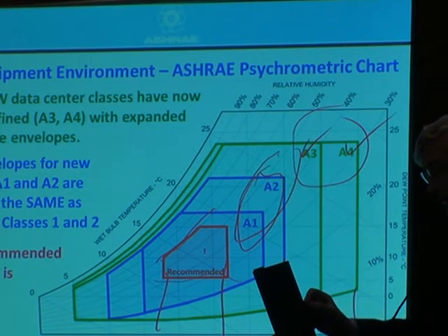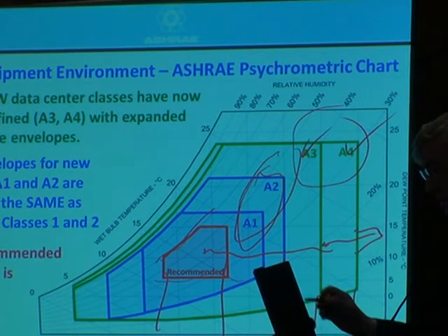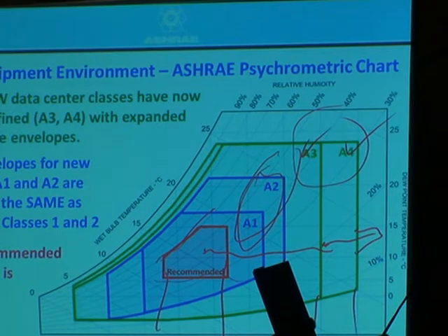So the process on this psychrometric chart looks something like this. It's straight across, no moisture. You're just sensible heating. So if I go in at 25C in the front, I may come out the rear of that server at 50, 55C. It is hot. So we all designed our equipment to do this. We designed it again for the inlet conditions.